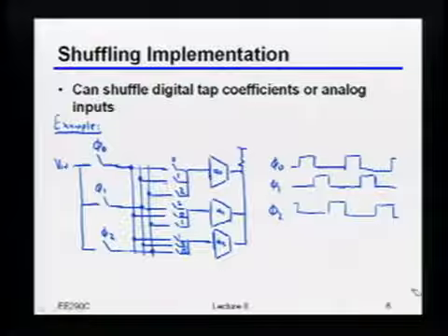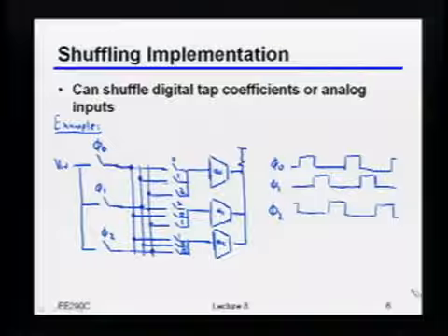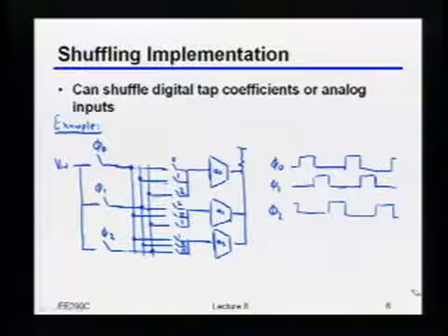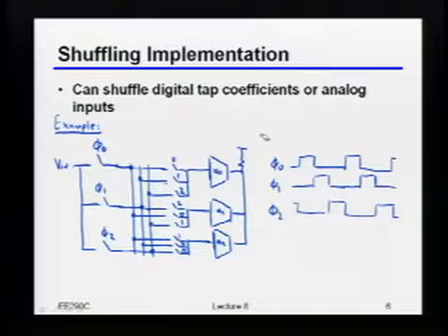So there are even things people did where they had a bidirectional system where in the forward direction it's your nice clean differential link, and the reverse direction, whose only job was to tell the transmitter what its equalization was supposed to be, was done on the common mode of that differential link. Okay, so again, it's a matter of being clever to get the information you'd like to send back to the transmitter. But that can actually be trickier than you may first think. Does that make sense? Or?